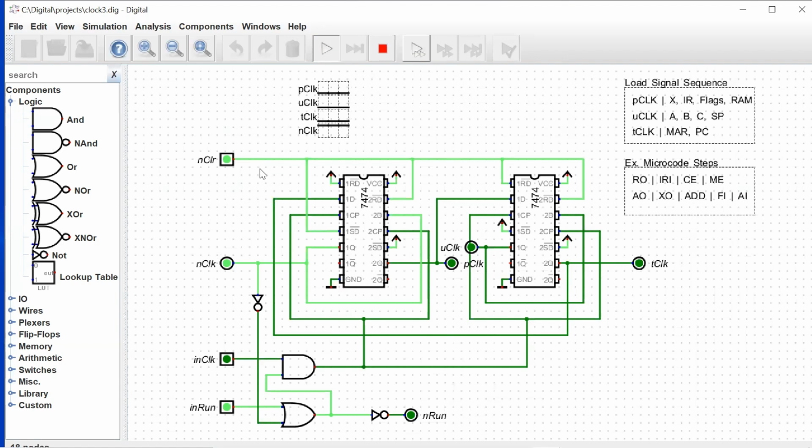the counter can run. Now we see up here that we have a kind of oscilloscope, and we'll get that going in a minute. What we've implemented here is basically called a ring counter. We have two dual D flip-flop circuits here, and each output feeds the input to the next D flip-flop.